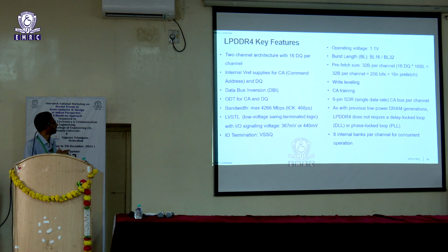We saw single channel versus dual channel earlier. If you have 64-bit data, if you are talking about a CPU's domain system, you need to have 8 DRAM chips of 8 bits that you need to be interfacing it with. And suppose your system can support 128 bit instead of 64 bit.